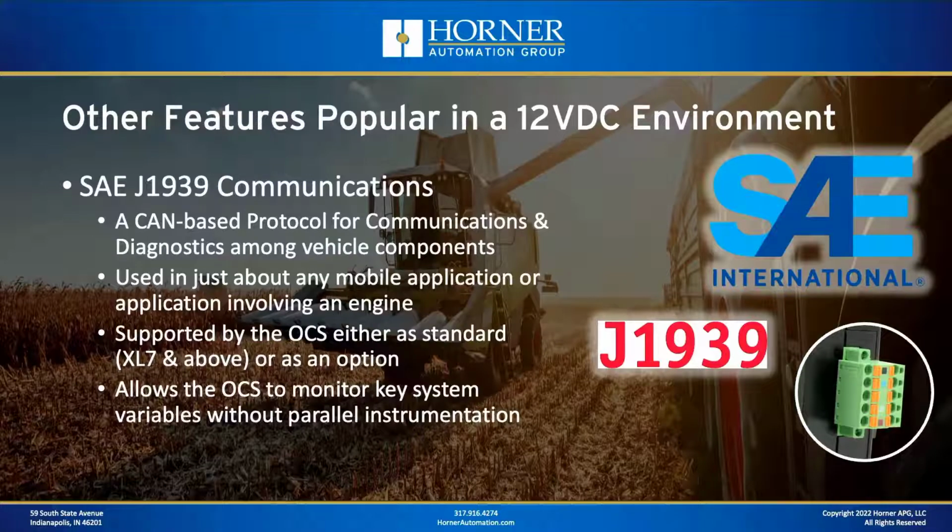By having J1939 supported, you now have the ability to monitor a lot of data that is being generated by the engine control module, temperatures and pressures and those sorts of things that are just available to monitor without having to add any kind of parallel instrumentation in terms of sensors and those sorts of things.